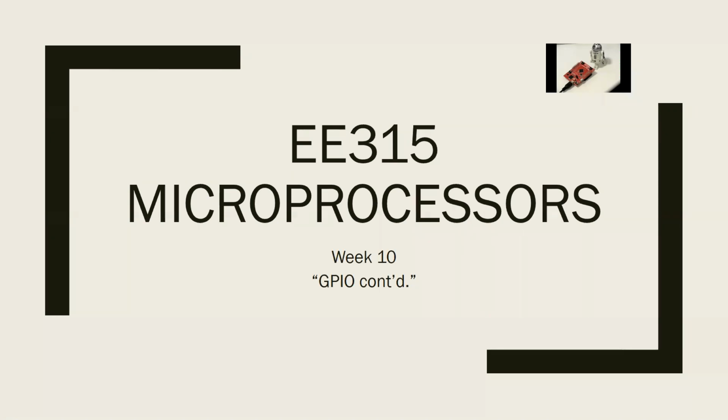However, while we're doing this, we are going to extend the configuration of the GPIO such that it's not only going to be LEDs, but LEDs plus switches. So we are going to initialize the port, specifically port F, not only for an output device like LED, but for both input and output. So we are going to be able to use both the LEDs and the switches, which are on the card. Okay, so I think you got the idea if you've seen the previous week's lecture. Let's continue.